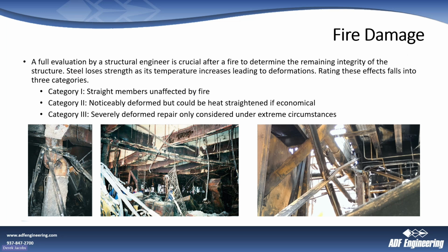So then we have fire damage. The steel guide puts categories on these. I don't know if some of you know, but fire, increased heat, will reduce the strength of your steel substantially. I mean, we've all kind of seen some of this stuff before, where as temperatures heat up, something that was originally sufficient for the load will now be softened enough that it'll collapse. The steel guides will put this in, when you're doing a fire inspection or inspection of a structure after a fire.